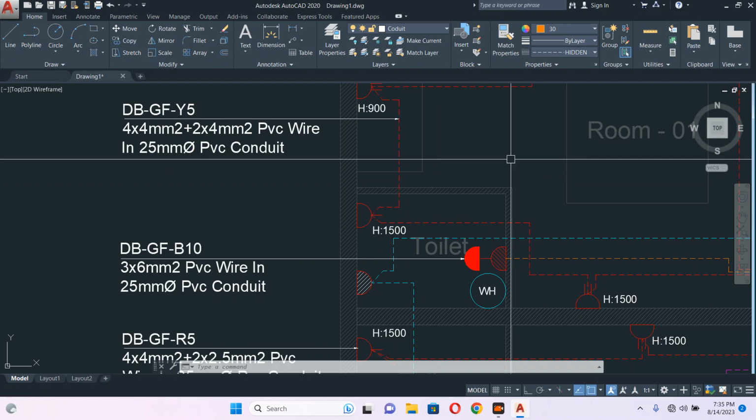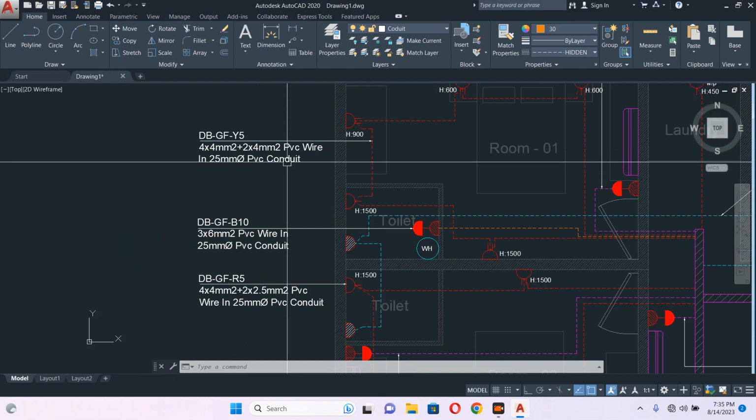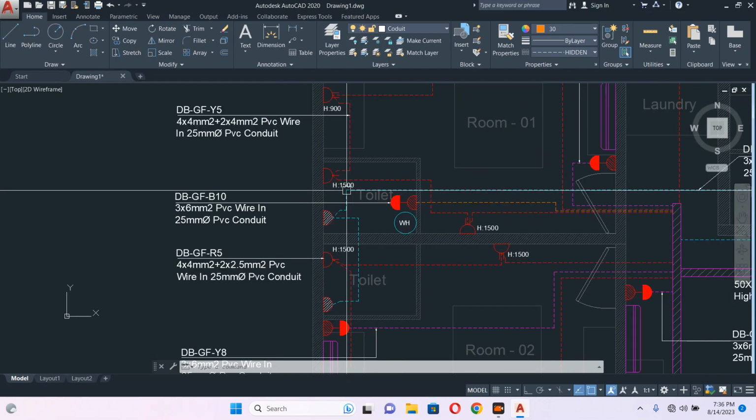First, they have to check the catalog from the manufacturer. Let's say in Sri Lanka we have Kalani Cable. And here we have Doha Cable and many Oman cables, Oman wire, something like that. They have their own catalog. In the catalog, they mention how much current each wire can handle. So as per that, you will choose your wire.